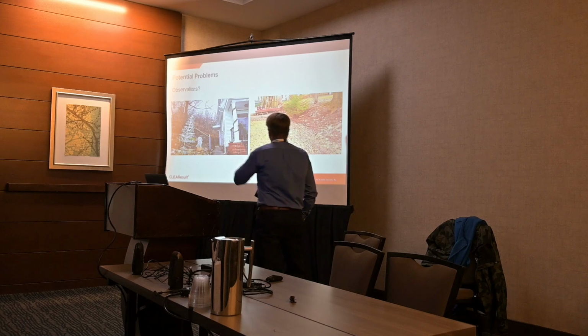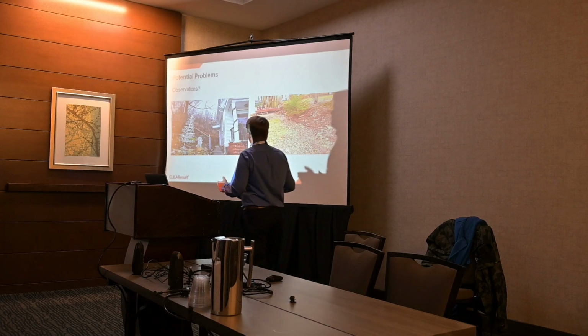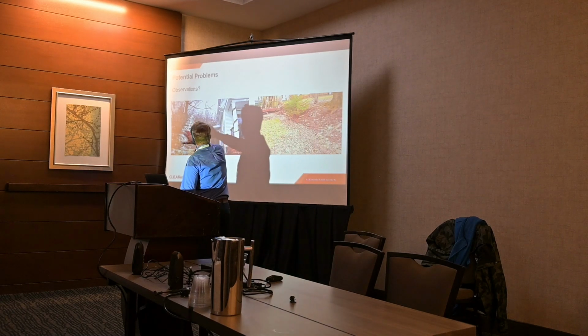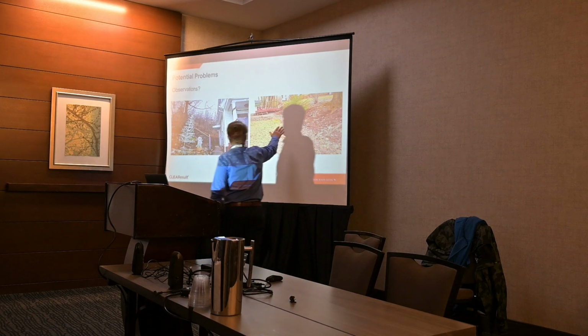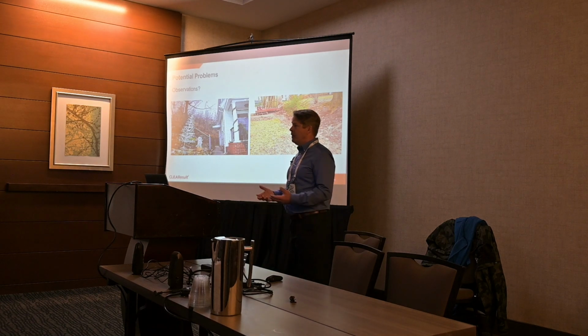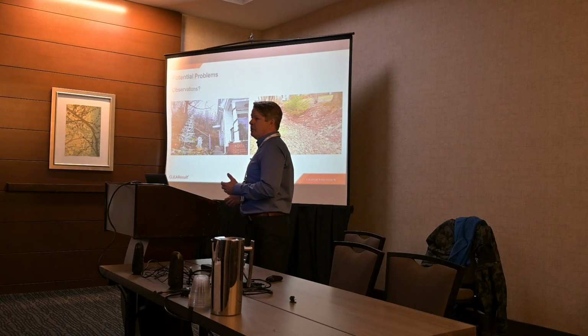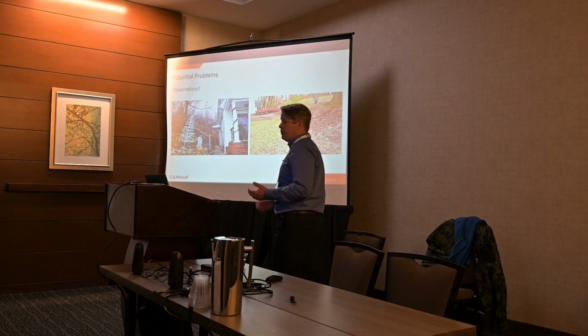Okay, and that kind of leads us to moisture in general, which is always a problem, right? We need the house to stay dry. When we look at this house over here, we can see that the grade is all coming towards the house, which means the water's going to run towards it. But they seem to know that because they've put sort of a hard pan here to drain that off, and the same thing over here. We don't want standing moisture in the basement, right? Because standing moisture evaporates, and when it evaporates, it comes up into the house. And if we tighten the house up significantly, then we're going to trap that moisture, and we'll have created a moisture problem.